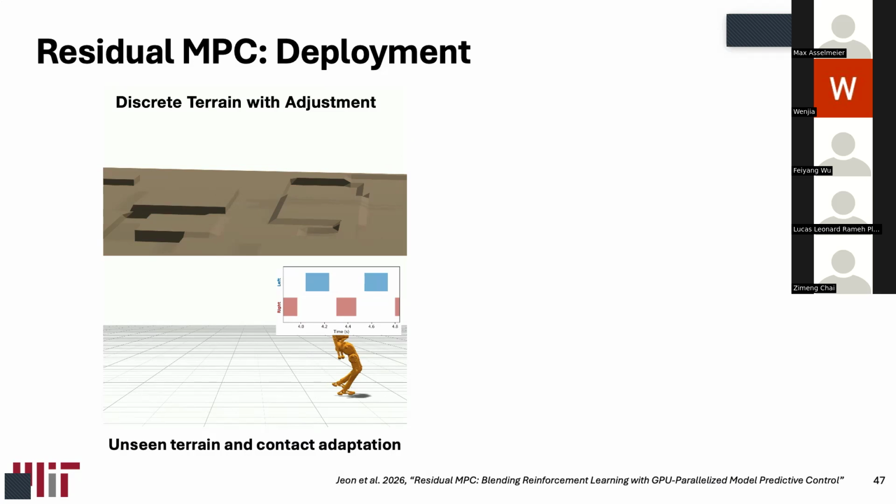Yeah, so the question was basically, am I making the claim that I can generalize this with the residual policy, the changes to these parameters? Generally, with MPC alone it fails, or I have to tune it more to make it work. The higher swing height will induce larger contacts, larger impulses, and the MPC is not quite as stable. I'm sure I could tune it to cover that case, but I don't want to emphasize tuning too much. Let's try not to tune as crazily as we often have to.